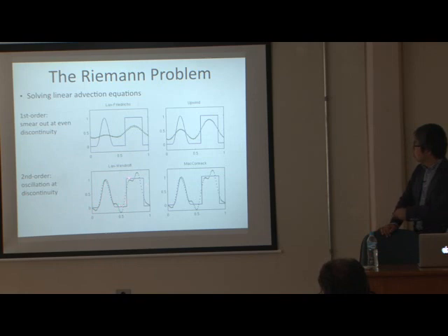We see something following the shock type structure, but with some undershooting and overshooting. We say this kind of structure is oscillatory. We previously used the Lax-Wendroff scheme many times, but this scheme also has problems around the shock wave structure. The smooth structure is maybe okay, but for shocks it is definitely not usable.